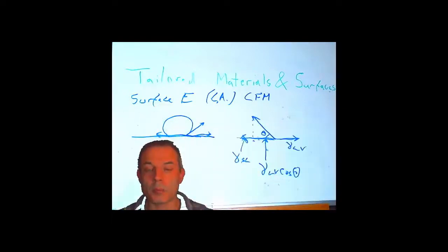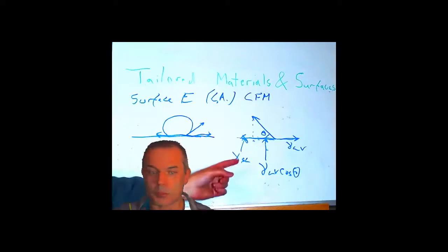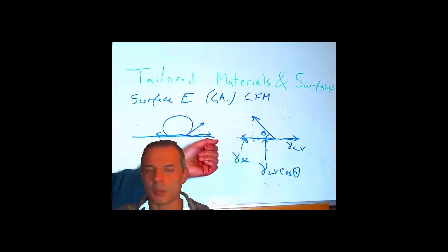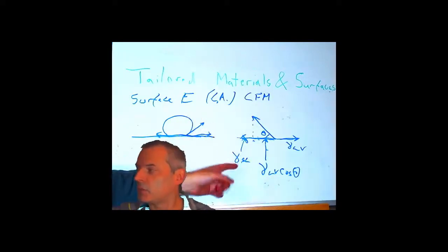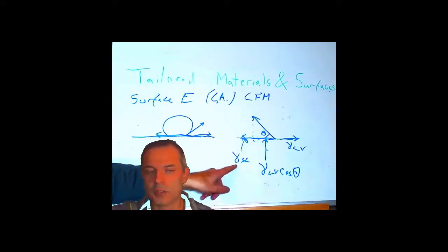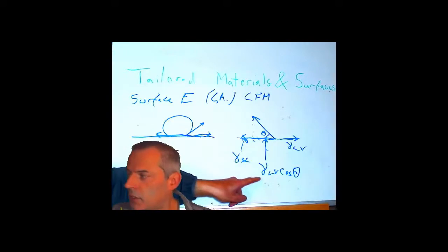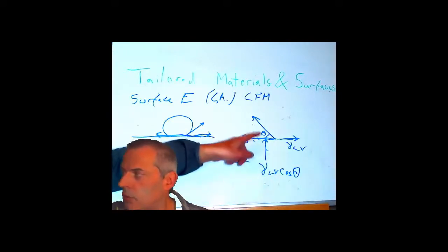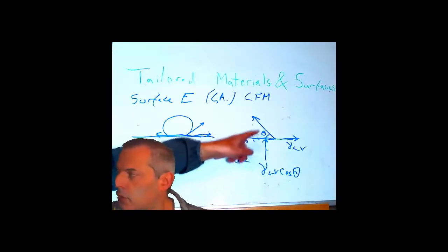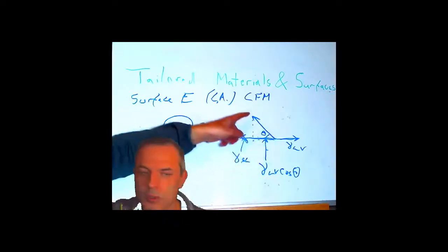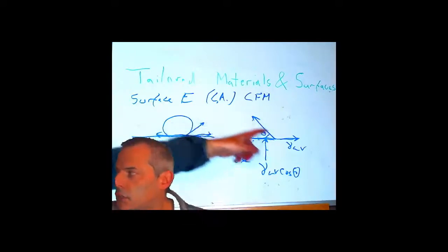in plane. So moving over here for a little bit, we have the possible forces. We've got the tension of the solid liquid pulling in this direction, the tension of the liquid vapor multiplied by the cosine of the angle, because that is the length of this side. It's the cosine of this angle, because this is the direction the surface tension is pointing in.